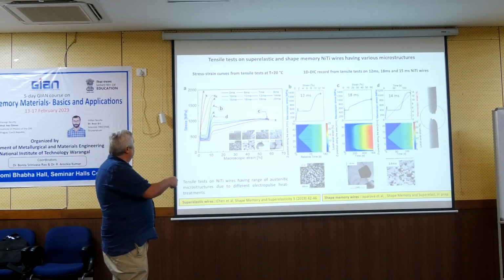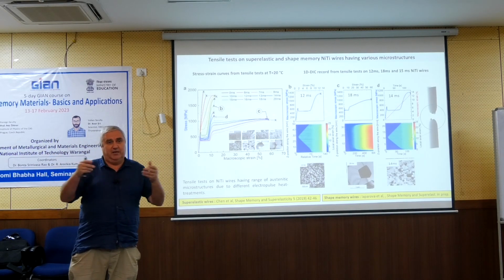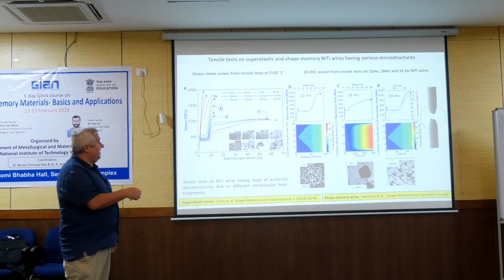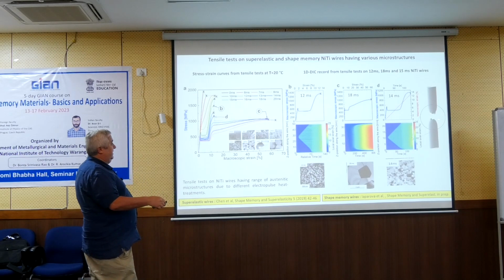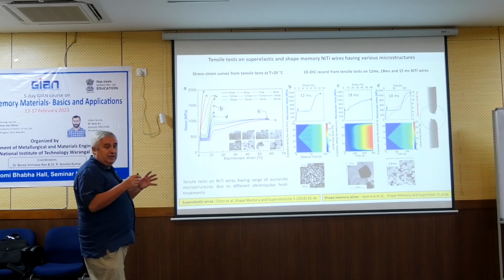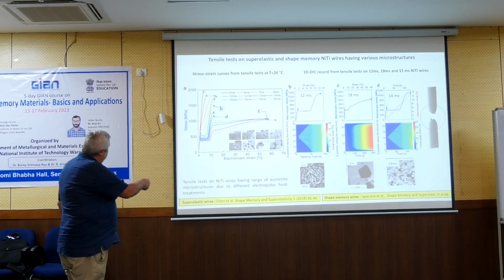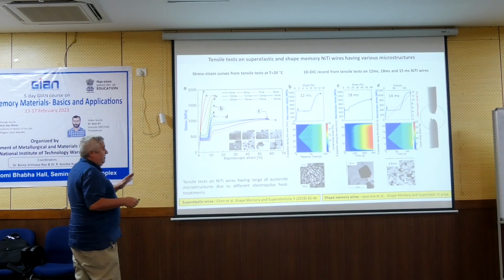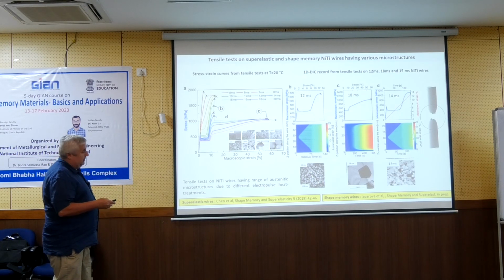It looks brittle because when you do the experiment and you don't look closely. But when you look at it, you will find out that suddenly the tensile deformation becomes unstable. It becomes localized in the neck, and the reason for this is the localized plastic deformation in the neck. We have very recent articles about that, but I will not speak about it now. But it is very interesting.